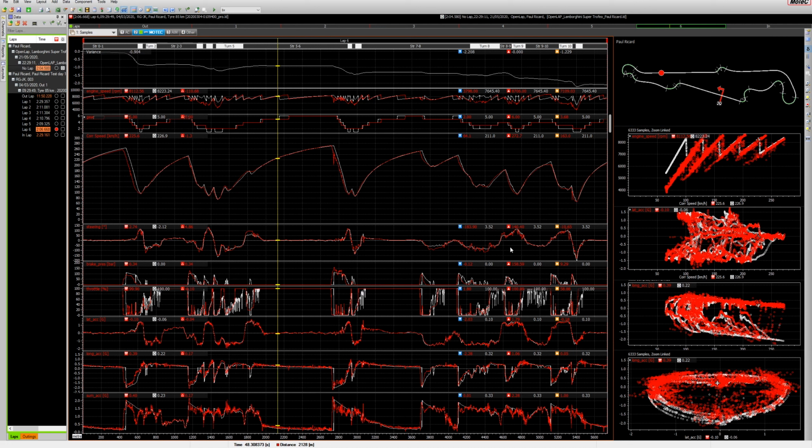In terms of steering, although we are using a very simple steering model after the fact, we can again see that there is pretty good correlation, but sometimes the real car seems to be understeering, here and here for example. In terms of brake pressure, again we have similar results, but with differences in the braking points. In terms of general brake application, we see that OpenLAP starts with applying a high pressure and then bleeding the brakes off, modulating the brakes to the grip.